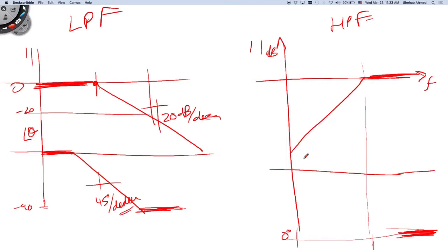And at low frequency, the capacitor is attenuating. This attenuation is due to the fact that you have a capacitor in there. It's not due to the fact that you have a resistor. Resistors don't do much, right? They set the time constant, basically. But what is doing the action of attenuation is the fact that capacitors are able to change from short circuits to open circuits. So when they see something they don't like, it's an open circuit. When they see something they like, they let it through. They play with it, right?